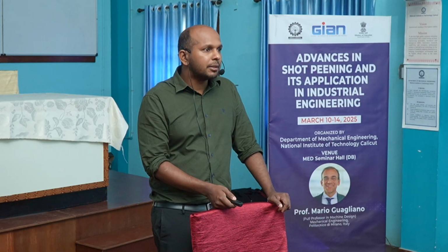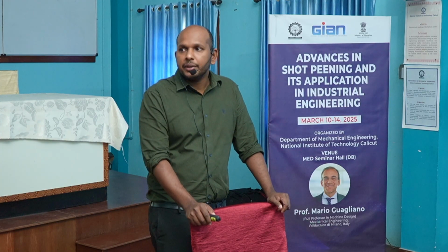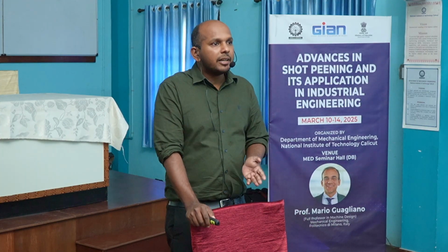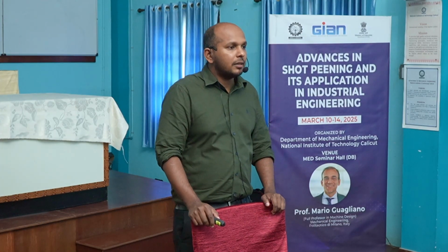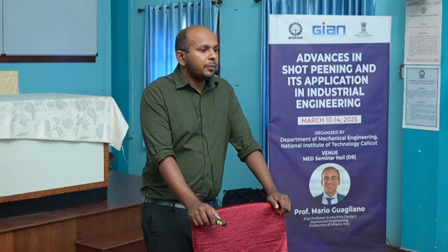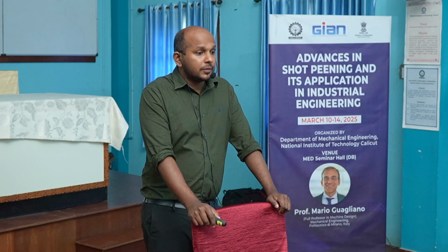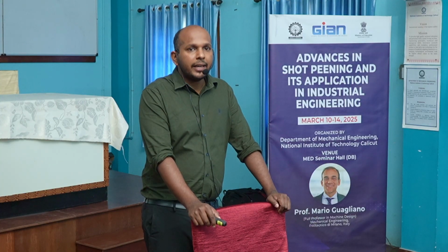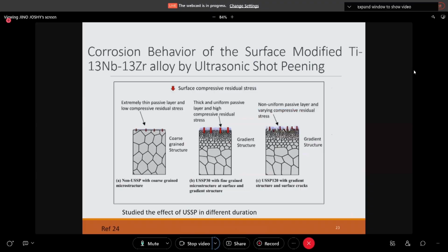And we are comparing the 60 and 120 samples. Basically in this study, they took the titanium niobium zirconium alloy and did the ultrasonic shot peening. Then they varied the time duration. Initially, they did not do it, that is the 0 sample. Then they did 15. They selected periodic time periods, and they exposed this material for 15, 30, 60, and 120 time periods.